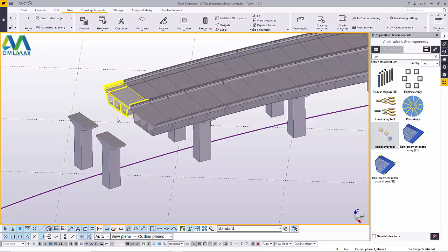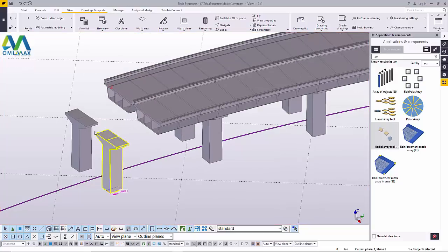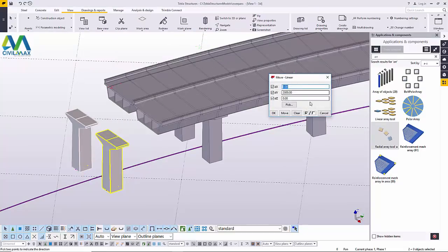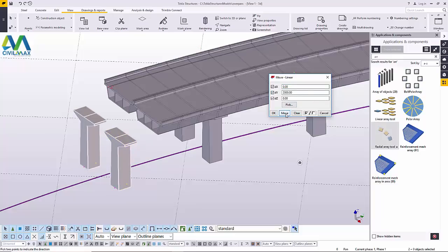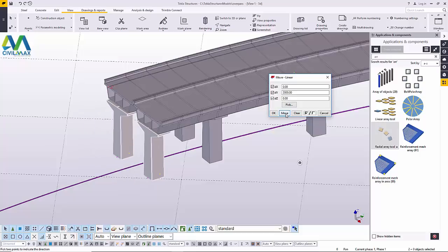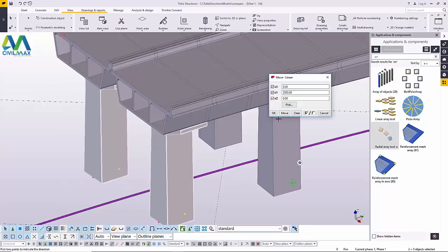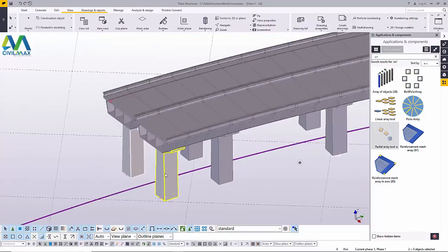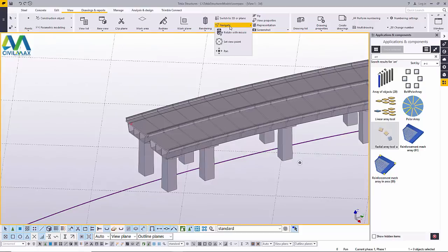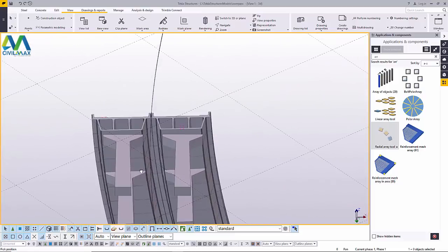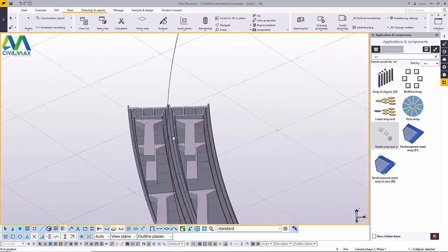We'll use the y-axis. Now we'll select on this, select on that, press Ctrl and come to move spatial and pick on mirror, and we'll use the y-axis. We'll use 2 meters, and we'll just click that until we get to the bottom end of that. You can see that when I click more, that is now at the bottom end. Now if we click on empty screen, you can see this is what we have for now.